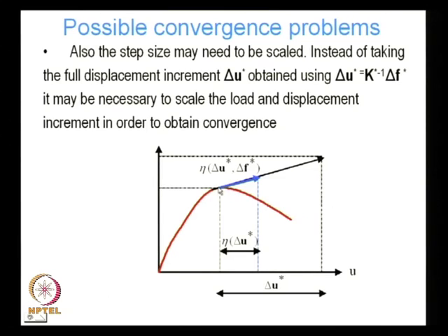If I divide the load increment by the tangent stiffness, let's think of 1D, so let's talk about division, then that tells me that I must move from here to here on the displacement axis. But once it moves here, you can see that the structure cannot respond because the load displacement curve is like this. So it cannot calculate an internal force to equilibrate the applied load, and then the problem diverges. If I have a situation like that, one solution is to scale the displacement increment, or maybe even the load increment.